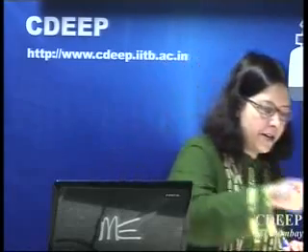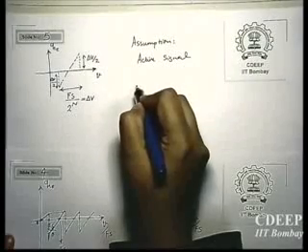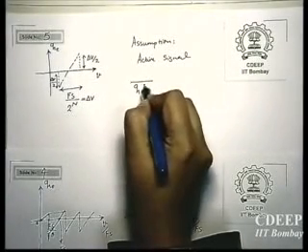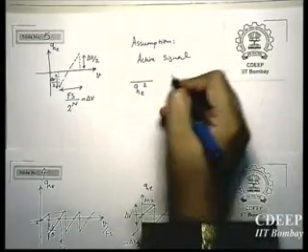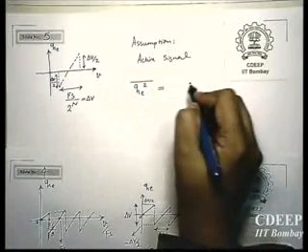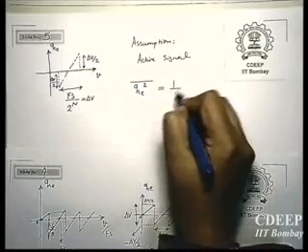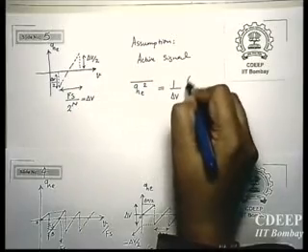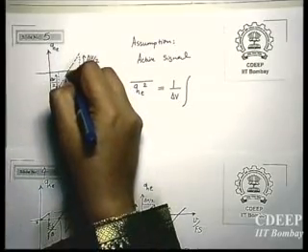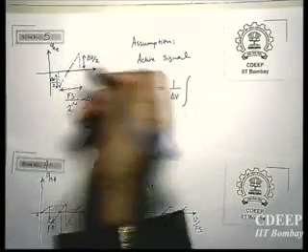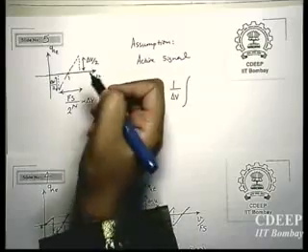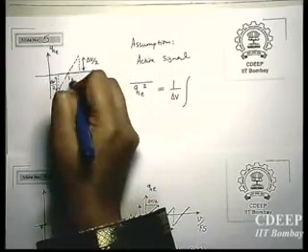So now we calculate the RMS value of the noise, or the average value of the quantization error. We look at one cycle as a function of the input, so we get the average over this range. If this is the middle value, you can consider some reference level, which doesn't matter.